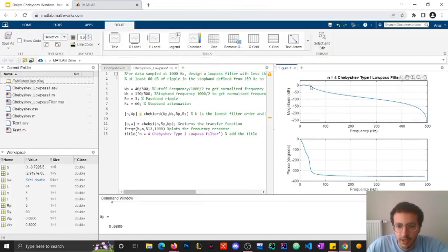Alright, so we have the graph right here. At around here, which is 40, you can see it started going down. So this is the cutoff frequency. It started attenuating, and it kept going down until around 150. This is the stop band frequency. After this point, all the signals are being filtered away by the low pass filter, and it keeps going down until it reaches the end.